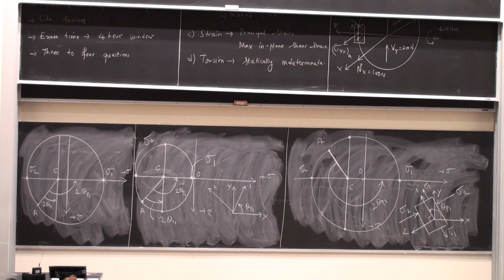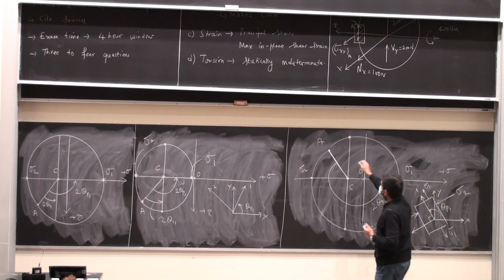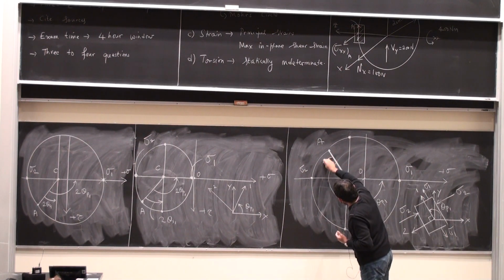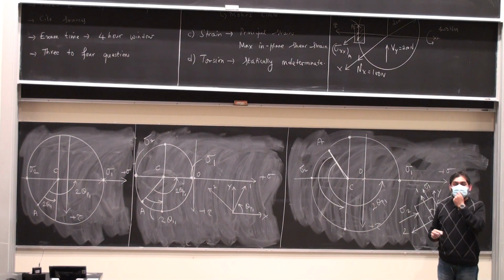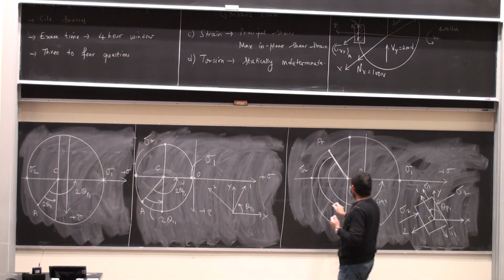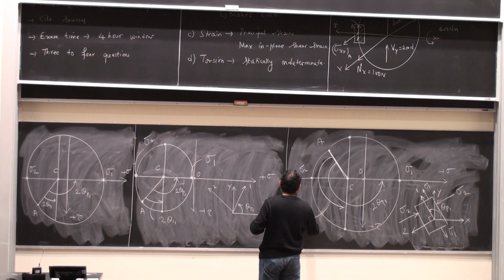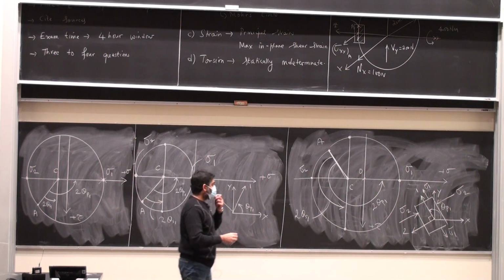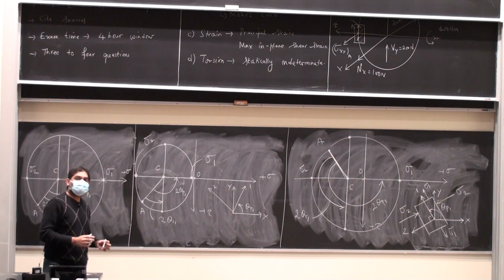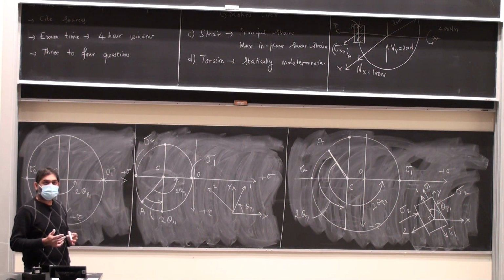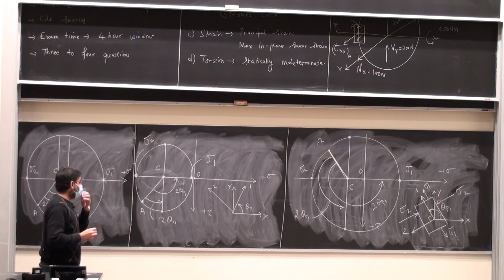And theta S1, so what's that 2 theta S1 here? So start from the reference line, counterclockwise to the first shear stress that you meet is 2 theta S1. Okay? And that's going to be an angle that is less than 90 degrees if I find theta S1, and likewise one can draw it out.